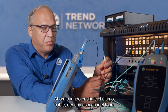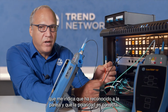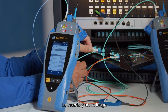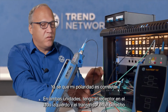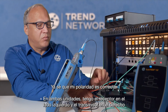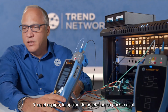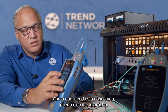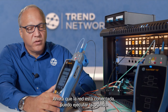So I should hear, when I plug in this last cable, the chime indicating that the partner finder is working and that my polarity is correct. So I line this up and insert it. And there it is. So there's my chime. So I know my polarity is correct. I have receive on the left on both sides, transmit on the right on both sides. And on the handset, the option to test has turned blue. So now that those are network connected, I can run that test.